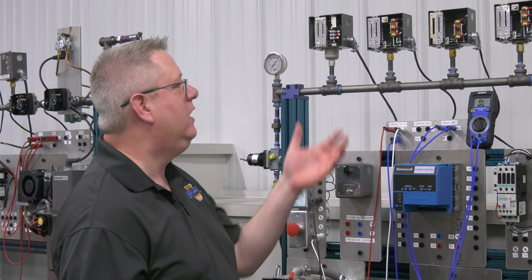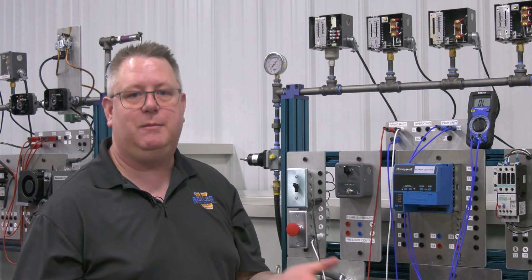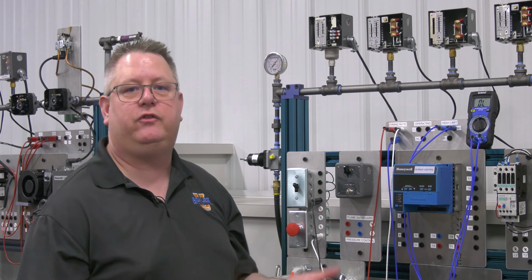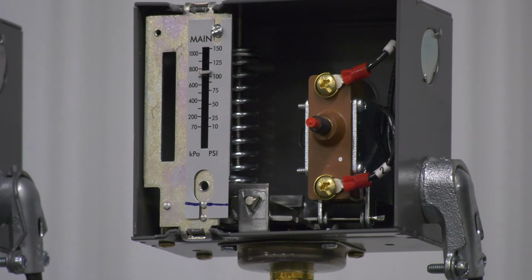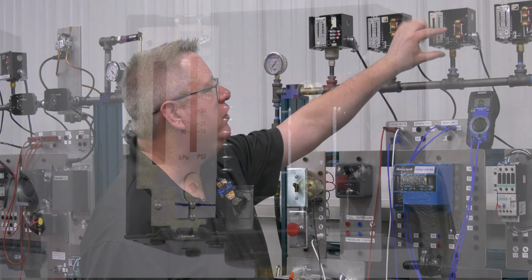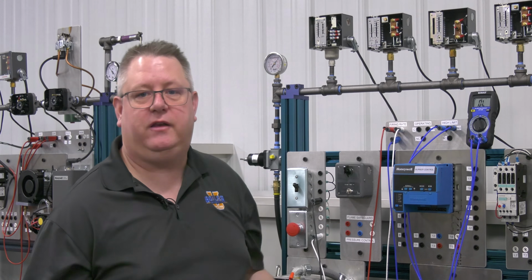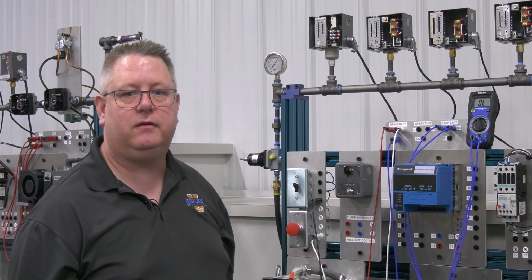Because obviously, if it was tripped and wired incorrectly, then it would be a permanently made switch and it wouldn't serve any purpose. So in many cases, the secondary high limit or the high limit switch will have no normally open contact. And that way it just prevents erroneous wiring.